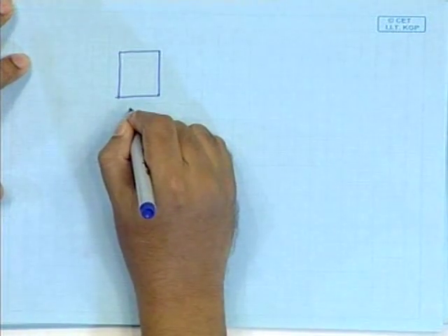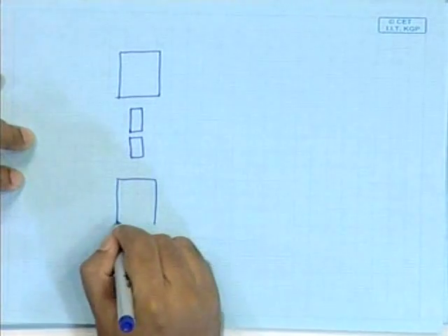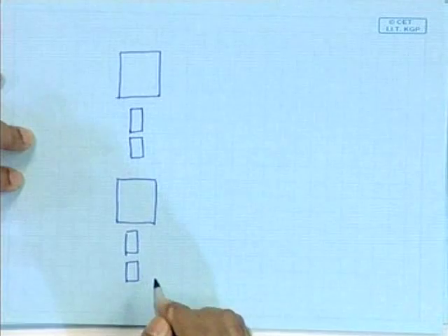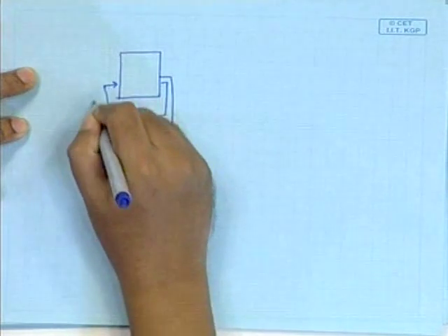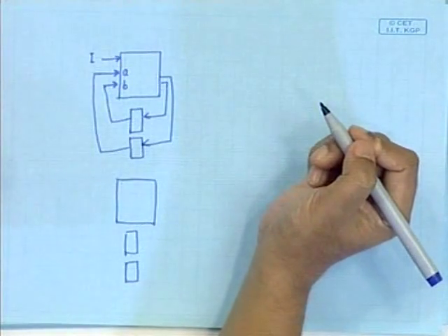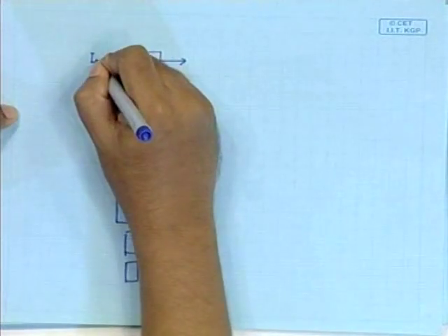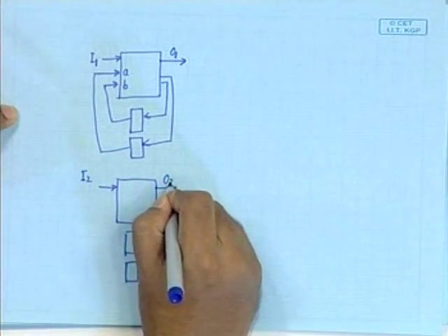That is, what exactly is being compared and how we are converting the two sequential circuits into a combinational equivalence checking problem. We are cutting out the registers and taking their outputs. So, let me draw it here. This is my machine 1, which has, let me draw this with two flops, and let me call these A and B. There are some primary inputs coming into the circuit, I1 and O1, this is I2 and O2.